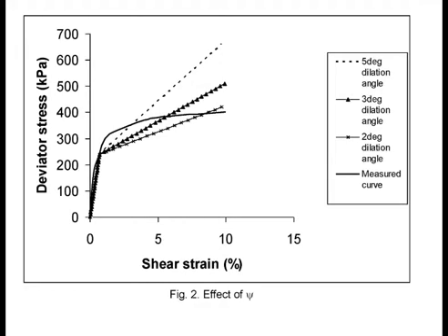It could be there. So there may be some argument, but if you use the stress path, that turnaround point tends to be quite sharp. Now, I'm not saying that you are wrong in doing it. You can use this point over here. But if you use this point, I would suggest you choose a Young's modulus that is representative from here to here. Now I'm able to choose a Young's modulus that's very high because I'm taking this to be the U point, and so I just take the secant modulus here.